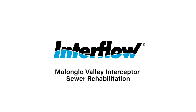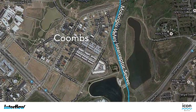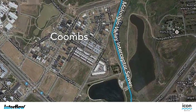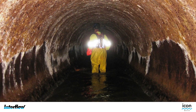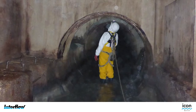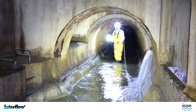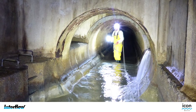Molonglo Valley Interceptor Sewer Rehabilitation, a joint project between Interflow and Icon Water. The project involved the structural rehabilitation of 913 metres of sewer, critical in carrying two-thirds of Canberra's wastewater. The precast reinforced concrete pipes were constructed in the 1970s and had begun corroding through exposure to sulfuric acid. With pipes measuring 2 metres in diameter, the project meant installing a structural liner larger than the product limits that had ever been attempted in Australia in a fully operational sewer.